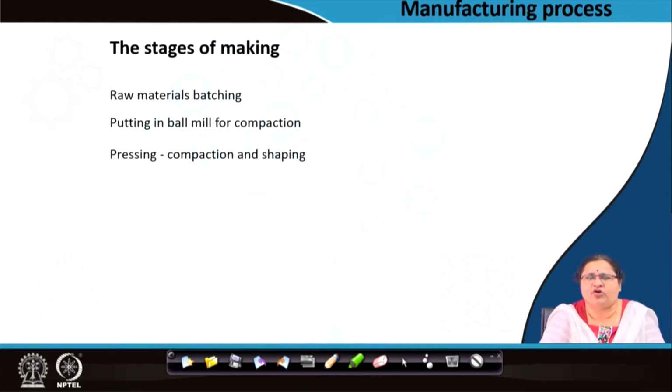So, these tiles are compacted to the maximum possible. The ceramic tiles are compacted to a certain extent, vitrified tiles are further compacted by hydraulic press. I will give you the figures. One is 300 MPa and the other is 350 to 400 MPa. These are required to make the material more and more dense, consolidated so that it gains strength. Nothing is fired till now. These tiles are also very thin, within 5 to 6 millimeters.